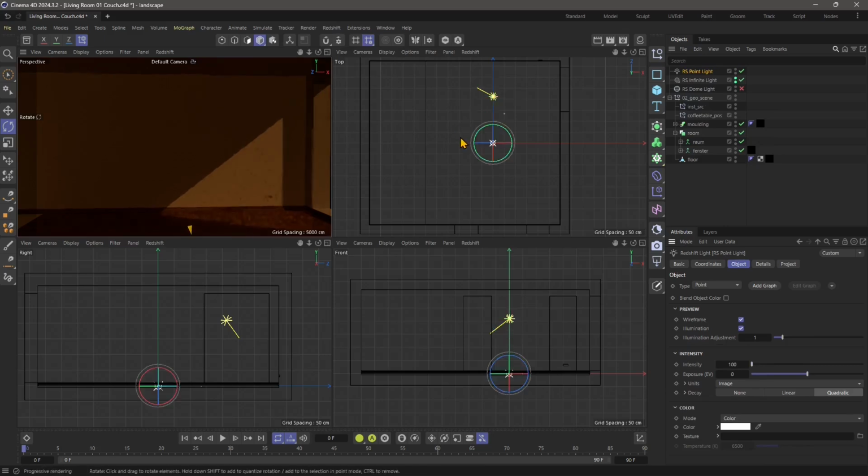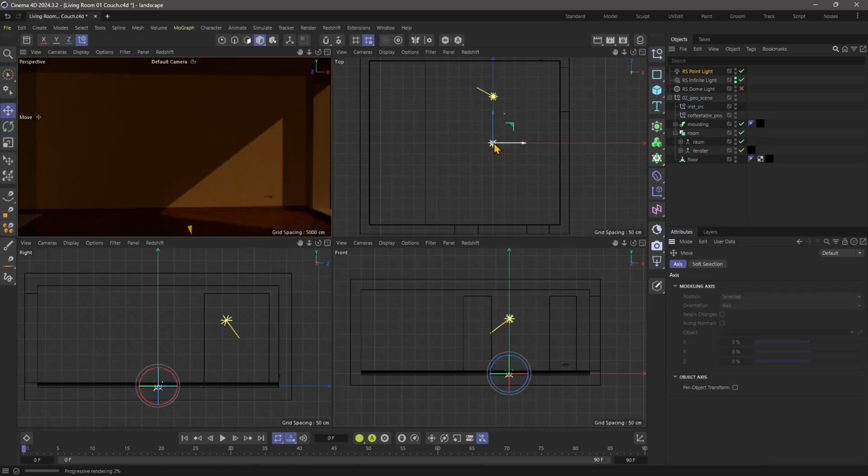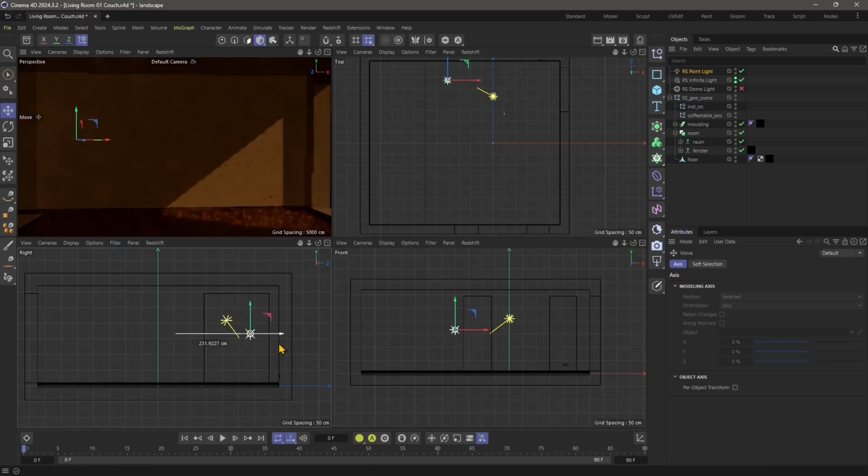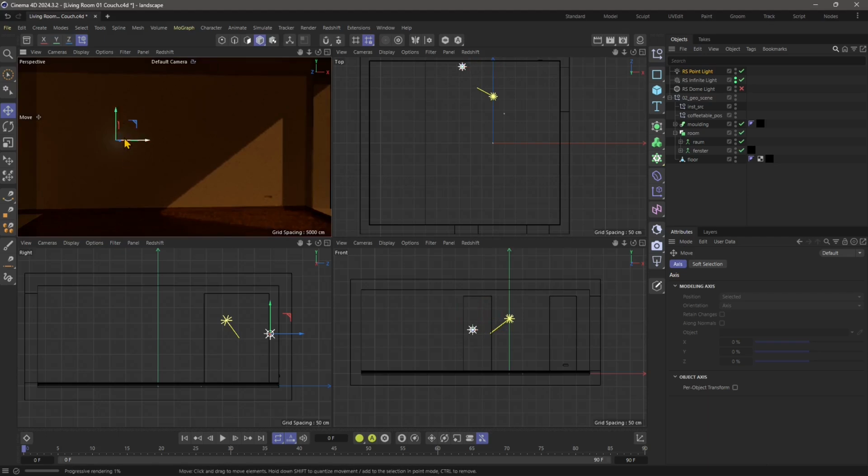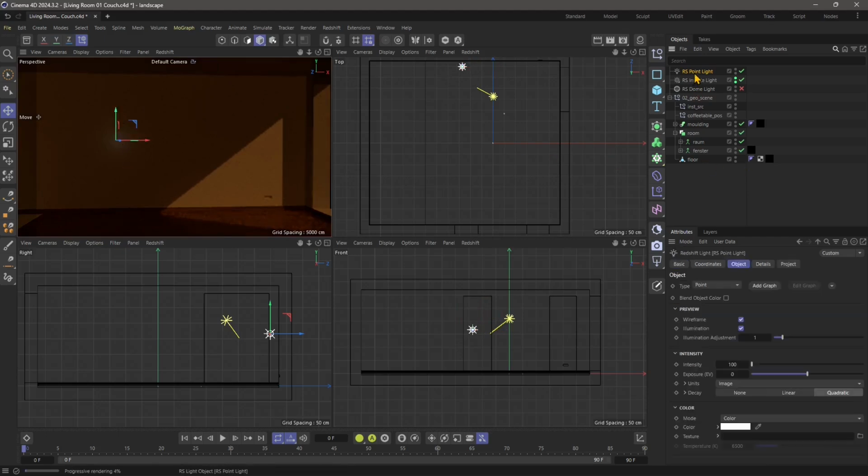Now I want to create a point light, and you see it's in the floor. So use the four views, because four views are really useful when you work with lights. So I want to position this light in front of my camera. You can already see the effect on the wall. It's looking like a ball. It's looking like a spherical light. And that's what the point light is, a sphere. It is projecting lights and shadows in every direction.